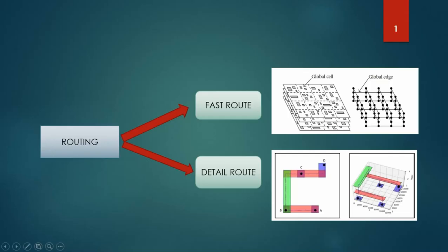In detailed route, we use some algorithm to find the best possible connectivity amongst all these points, that is A, B, C and D. What you see in the picture now is one of the strategies. The dotted line that you see inside these boxes could be one of the best routing topologies which has been obtained after some optimization in the detailed route stage. Things could get a little confusing, but I'll try my best to give the explanation and see if you can follow through.